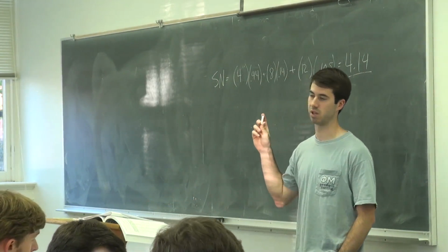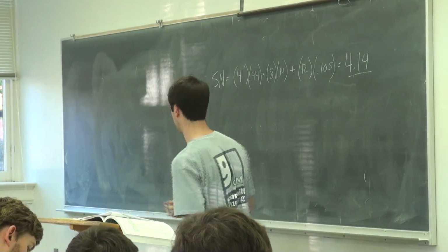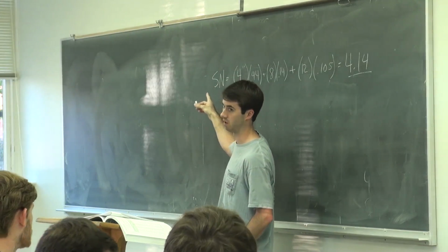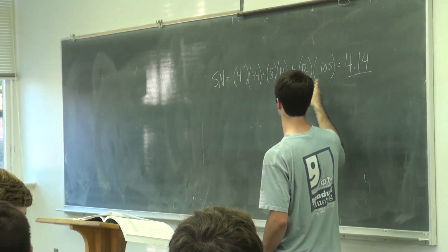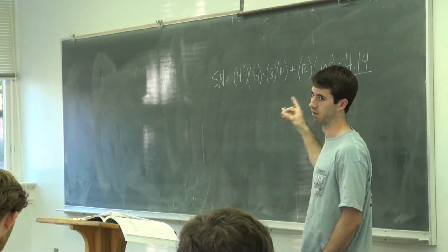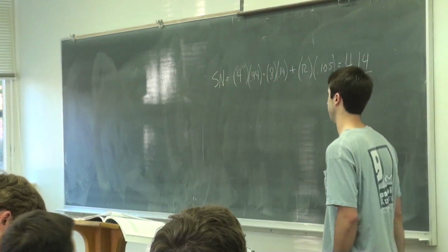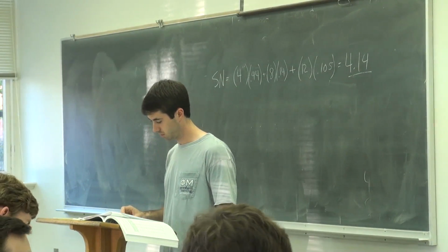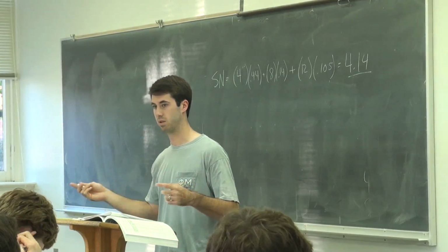Make sure that you keep the difference in your mind. Because if you were designing, you would take this equation and work backwards, take your required structural number, say it was 5, and then back-calculate all these different layer thicknesses given these coefficients. You would have to end up with a number bigger than 5. So right now this road like we have it would not pass. We have to increase something. Just make sure you keep those separate in your mind whenever you're doing analysis and design.